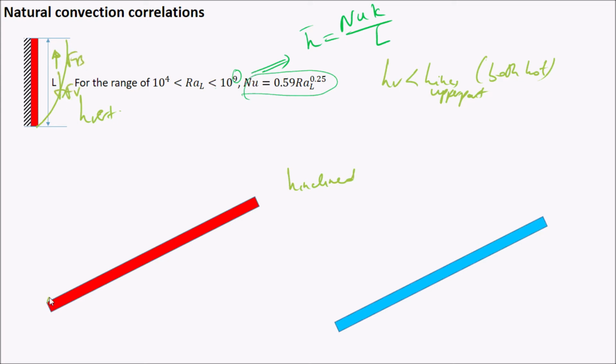But here you have boundary layer growing something like this one, and in that case you will have X component and the Y component of the buoyancy forces. Okay, buoyant forces. And since you have the Y component of the buoyant forces, it means that this boundary layer, if buoyant Y direction is very strong, okay, if it is very strong, it will break this boundary layer, and you will have something like this one. Okay, and this one is called the plume.